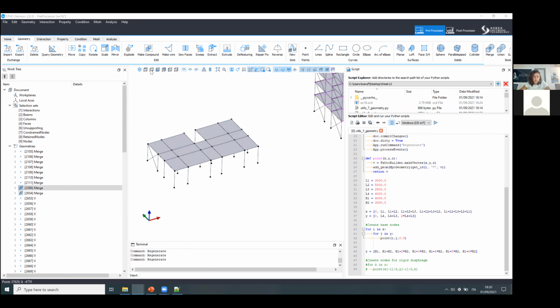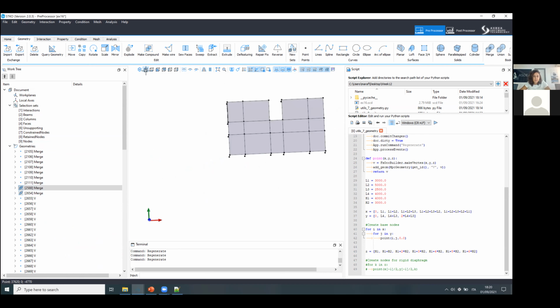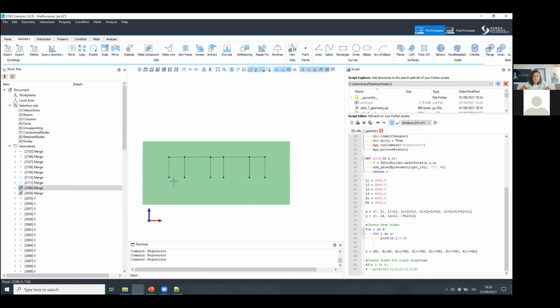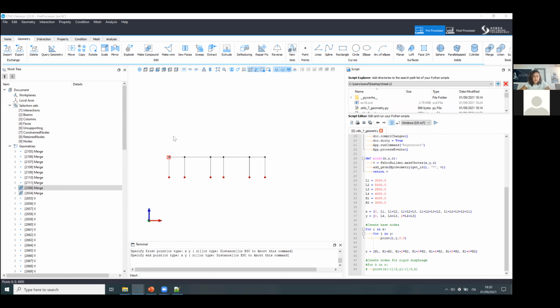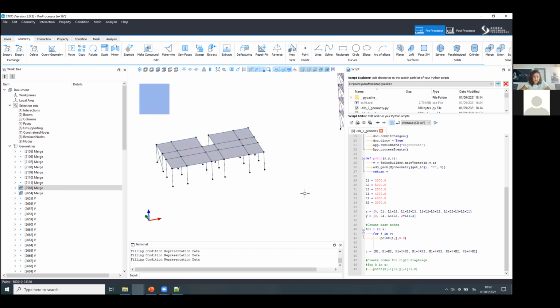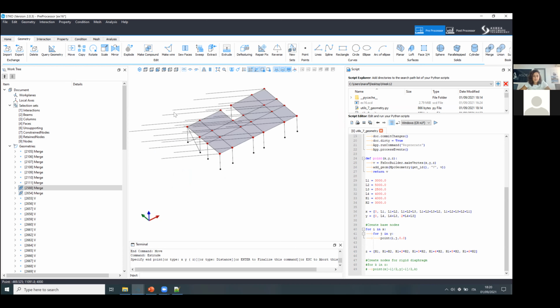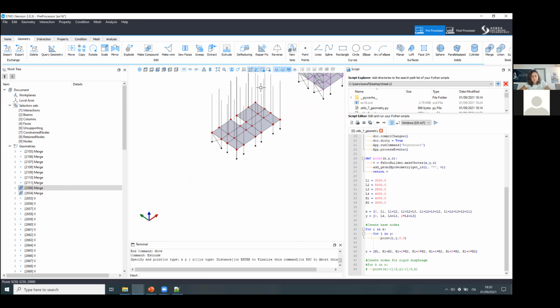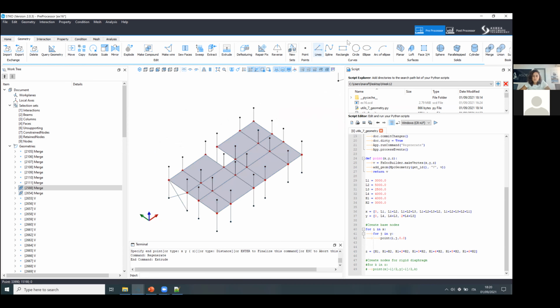Because as you see, for example, right now I lost my reference, but I can actually create it again very fast. Reselect all, deselect all the geometry, move these points up here, and then use them to extrude again our columns of 3 meters. So we go in the terminal and we type 3000. There you go. Same goes for the next floor.